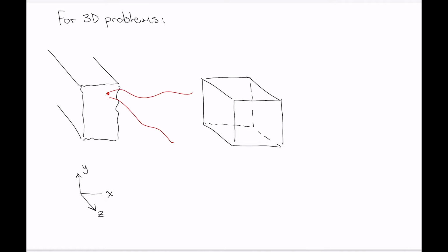So thinking about the different possible normal stresses that we could have here, we could have a normal stress that acts on the top face of that little cube of material. So that would be, just drawing these in as tensile, labeled sigma subscript y to indicate that it's a normal stress in the y direction, right? And the naming convention is pretty obvious here. So this is also sigma subscript y in order for the element of material to remain in static equilibrium here.